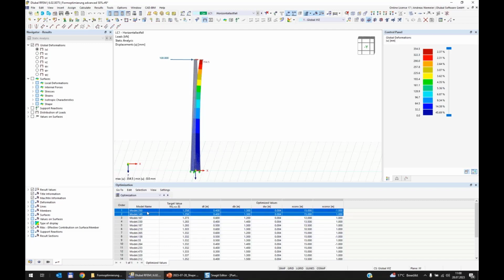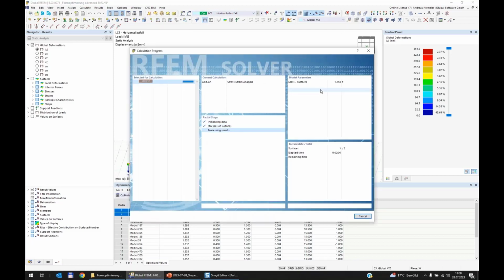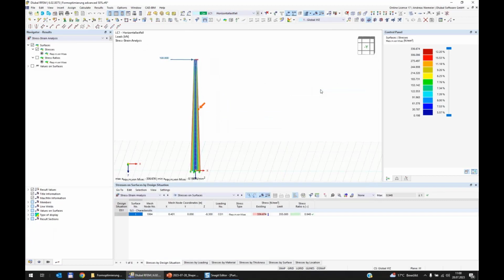And finally, it sets exactly the best fit parameters and calculates the stress check. And if you run the stress analysis here, I think you should get a utilization smaller than one. So here we have maybe 95% utilization. And this brings me now to the end.